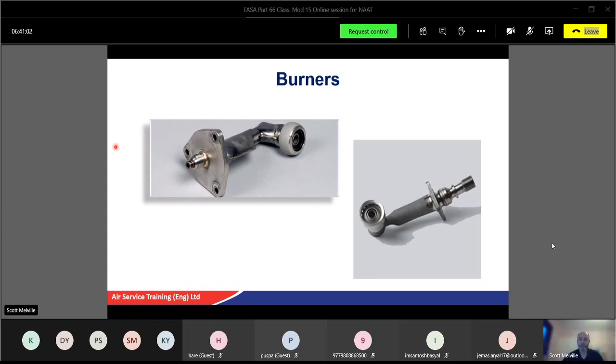Okay. Swirlers, again, inside some of the burners, not these ones, but you see some swirl vanes there. They can be cracked or missing, or burnt away potentially. Again, for security, you can't really check it because you can't physically get in there. But certainly before you fit any, if you take them out for whatever reason, check them for security. But once in there, you can only visually check them using borescope equipment.